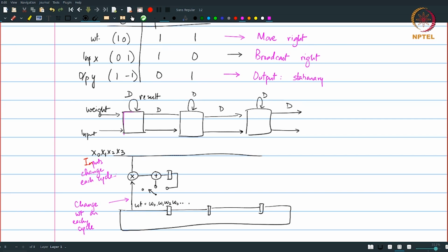Also note in this case, one more thing, you might wonder why you need 3 different processors if after all everything is being done on the same processor. That's not entirely true. Effectively, what this is saying is Y0 will be computed on this first processor, Y1 on the second one, Y2 on the third. Then again we get back to Y3, Y4, Y5 and so on. Okay. So in other words, the 3 processors are each computing a different processing output by appropriately broadcasting the inputs as well as moving the weights from one place to another.